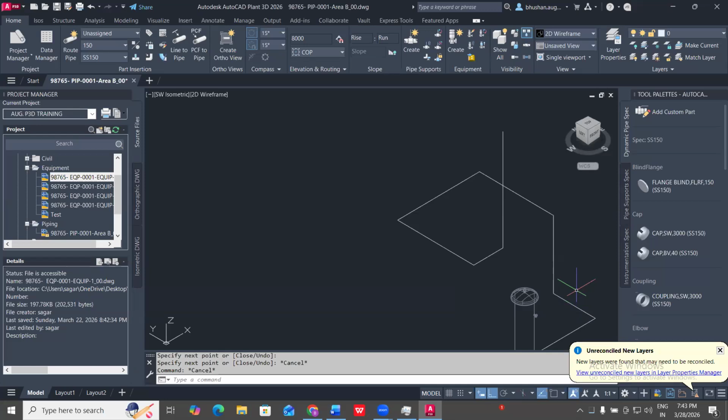You draw a polyline in AutoCAD, just a regular line, then select it and use the Plant 3D command to convert it into the pipe. The software will follow the path of the center line and place the pipe and fittings accordingly. This is very useful when you have a concept pipe route and want to plan it first before doing the actual 3D routing, so it takes less time to convert.